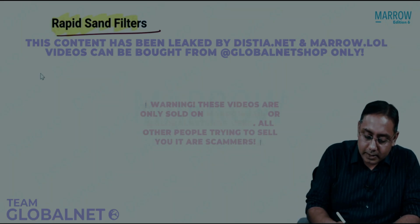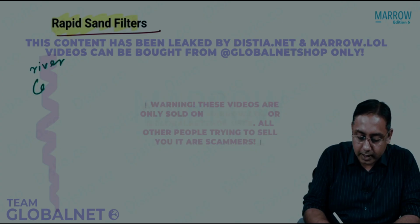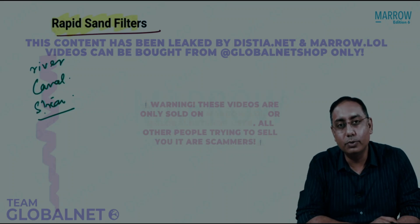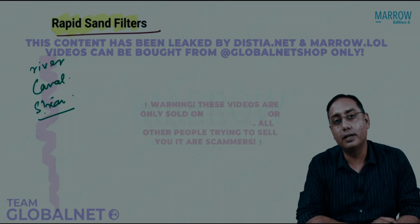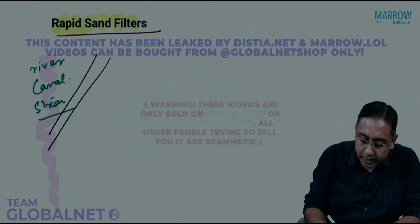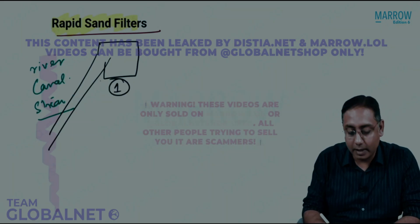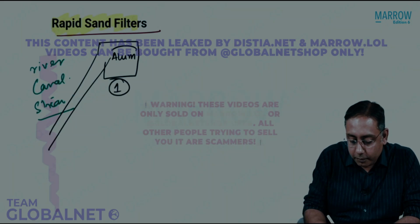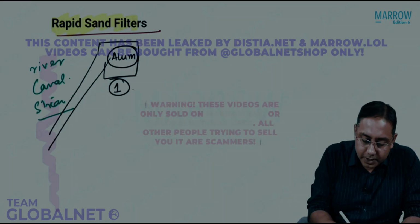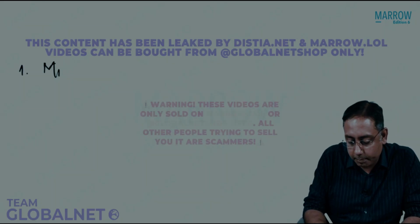What happens is, let us assume there is some river, or there is a canal, or there is a stream. So what water do we use normally at the municipal level or at the public level? We always use the surface water. Take it to a certain height, and at that height we mix it with a chemical called alum. That is your first MCQ. So, first MCQ, what is this first chamber? This first chamber is called the mixing chamber.